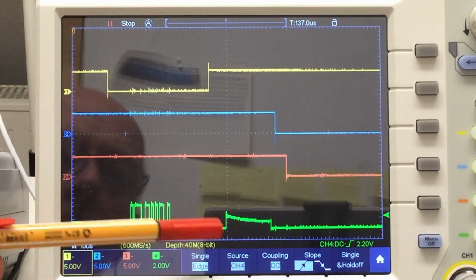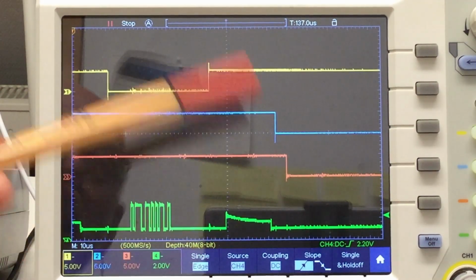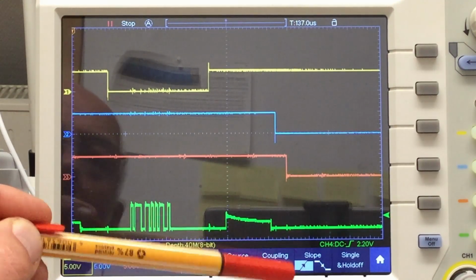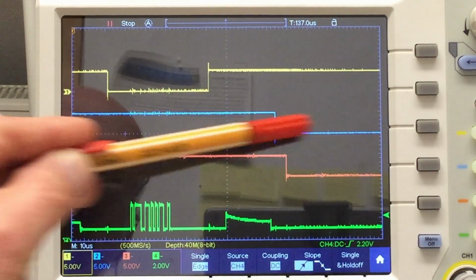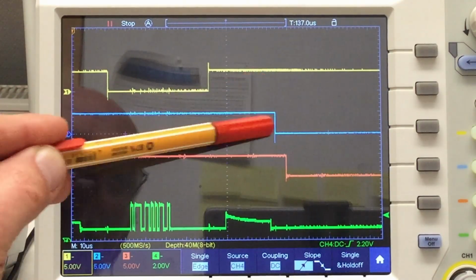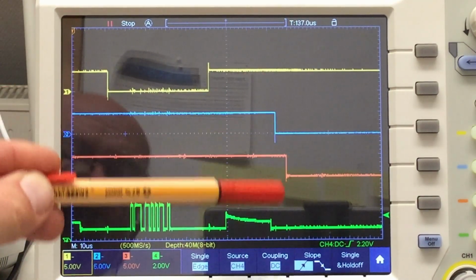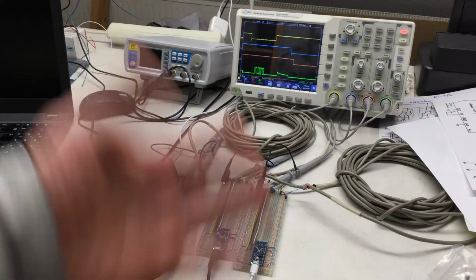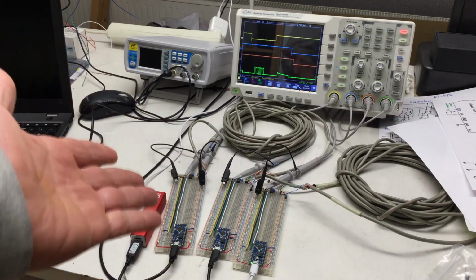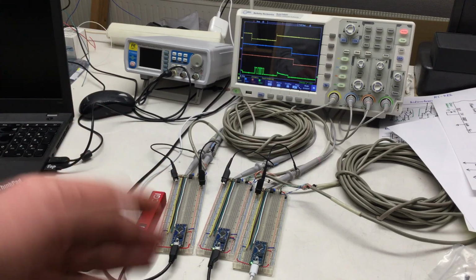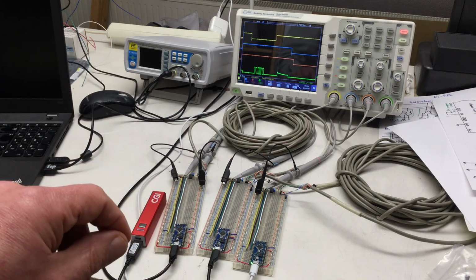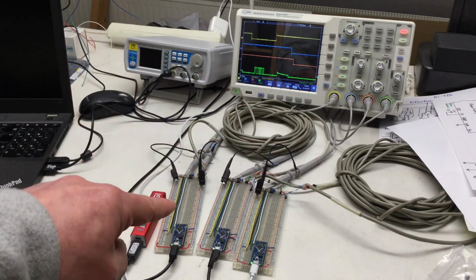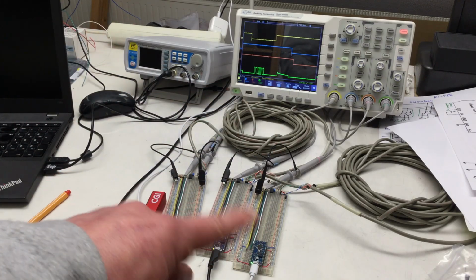And the usual protocol dance starts again, transferring control back from slave 1 to the master. After which both slaves enable their receivers again. And yes, I could have optimized the timing here at the end a bit more. That's it for today. We have now, thanks to the timeout in the master, a robust communication. And we have a real bus, that is, we can now address multiple slaves.